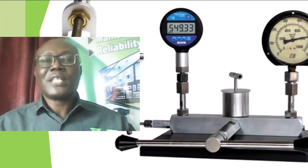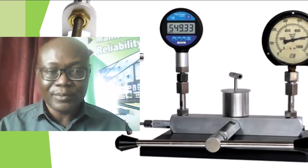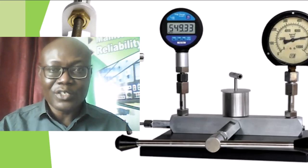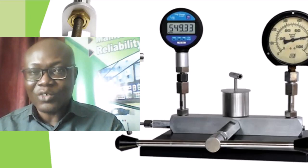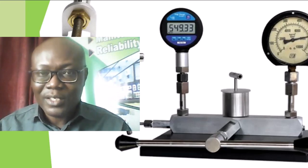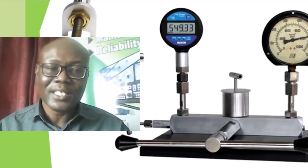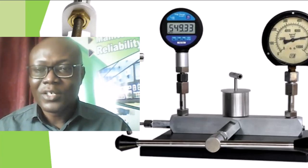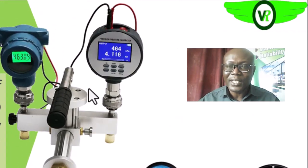So basically, in calibration, what we do is the comparison of the instrument reading with that of a reference instrument or a master instrument. Are we getting it? And then make the needed adjustments. So what I'm trying to say is this: assume that this is the instrument that we want to calibrate, and this is our master instrument.